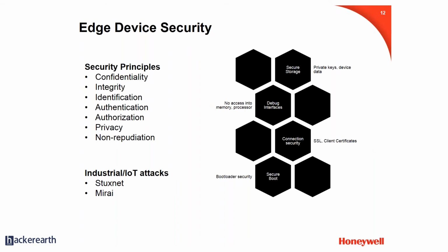So that is another design consideration you have to take, where you don't let anyone access your device. So your JTAG ports, all of that, have to be fused so that nobody can access. Then you have connection security.